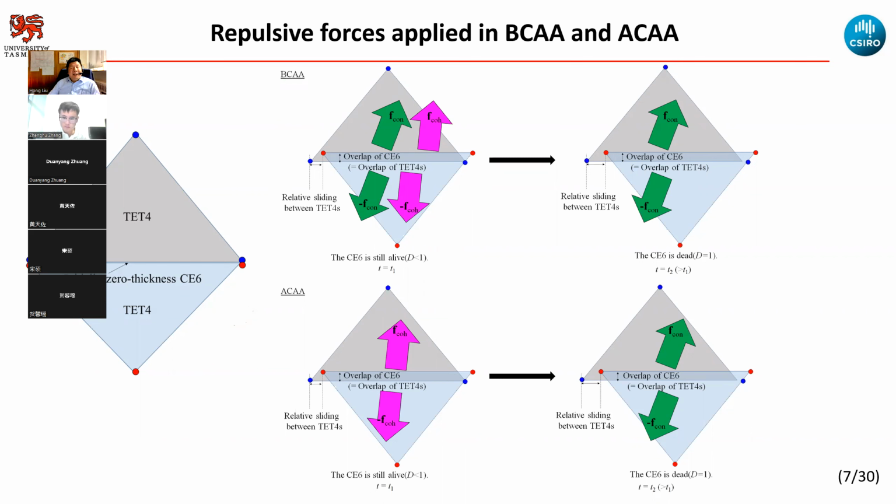When we do this transition from the cohesive repulsive force to the contact interaction force, we need to control it carefully. If you do not control it carefully, it will cause a spurious failure pattern. What we call spurious is, like in an explosion, as long as you load the sample, it fails everywhere.